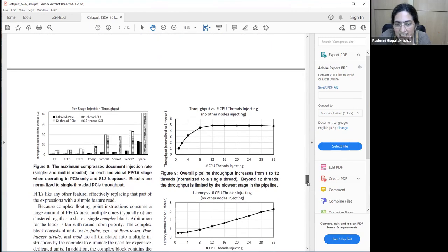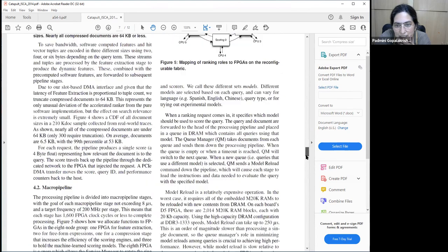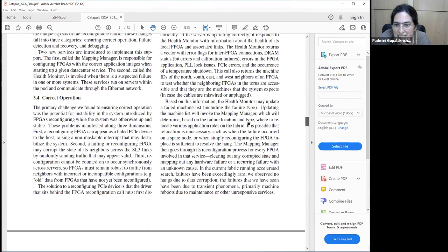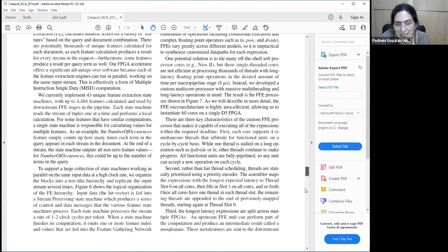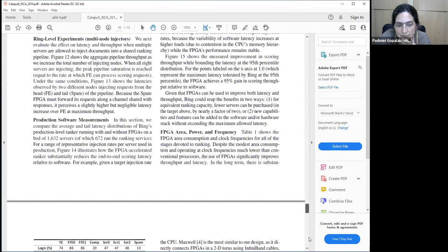So because of that, they have this kind of architecture where you have multiple cores sharing a functional unit that does floating point computation. And then you need an arbiter to figure out which core is using the FPU unit at that point in time.